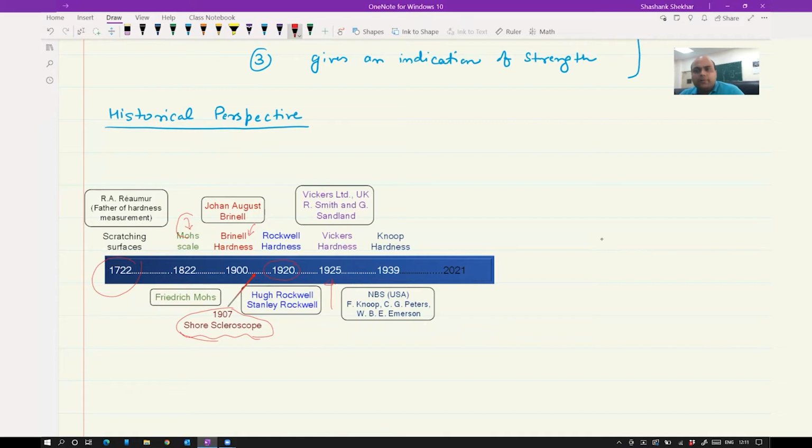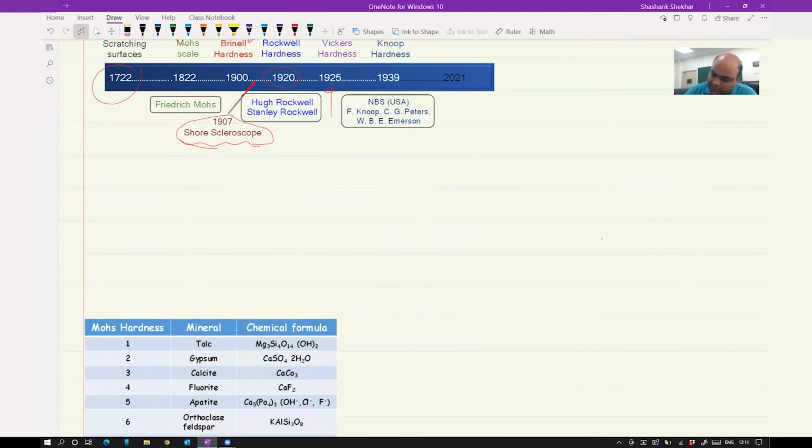Now we are talking about instrumented hardness like nanoindentation. Even in Vickers microhardness, you can measure using the instrumented indentation technique, IIT. But we will focus mostly on scratch hardness, then rebound hardness, then Brinell, Rockwell, and Vickers hardness. This is how I'm going to talk about the progress of the topic. So let's start with scratch hardness.